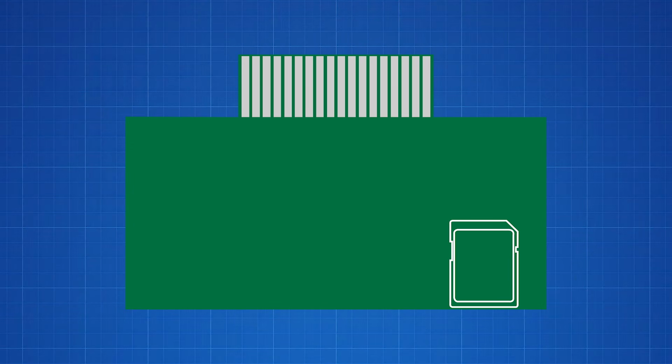Flash storage isn't fast enough for the console to use directly, so flash carts will also have a memory chip. The game image gets loaded into this chip, and this is the memory that's presented to the console's address and data bus, making the system believe that it's the cartridge ROM.